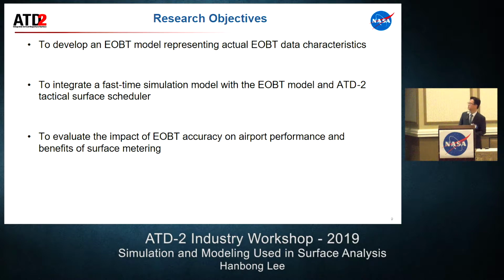So here are my research objectives. First, we developed an EOBT model to represent the actual characteristics of the actual EOBT data patterns. And then we integrated our fast-time simulation model with this EOBT model and the ATD-2 tactical scheduler. And then we evaluated the impact of EOBT accuracy on the airport performance and the benefit of the surface metering using this fast-time simulation platform.